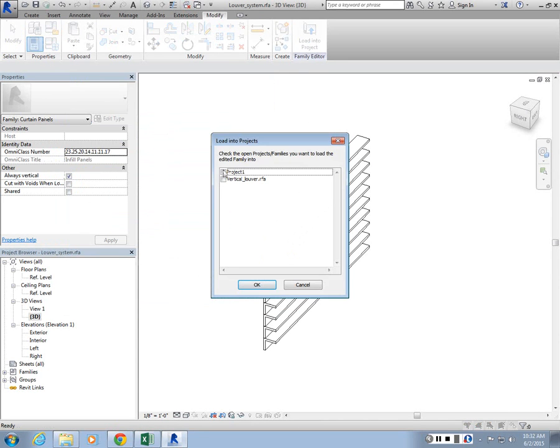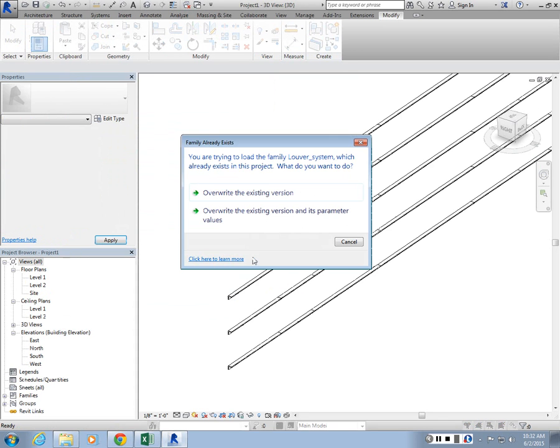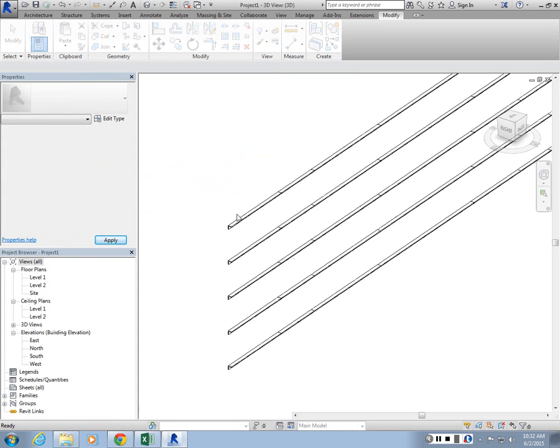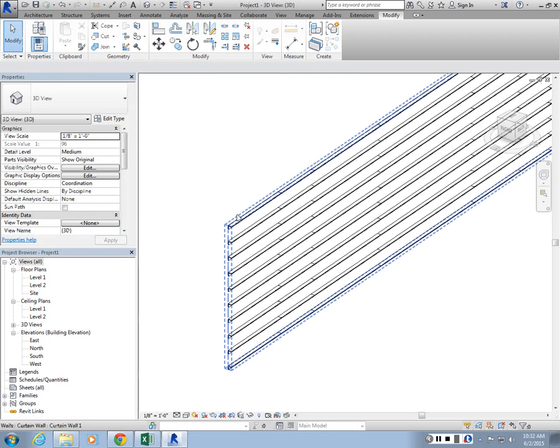So, in the curtain wall panel, when I go to family type, I still have the number of louvers parameter that I set up. That was the old one. So yesterday we created the array inside the curtain wall family, and today what I did instead was do it in the line-based family. So when you bring it in, that parameter is located here. So you need to create something else here to link it back to that.